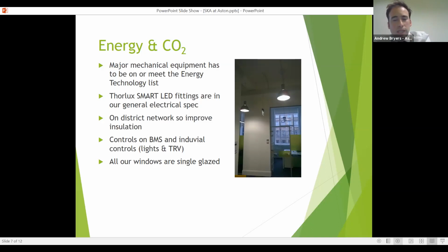We only have single glazed in our main building where we've done the main projects so far. We haven't done it for any other building, but they're all really drafty. So what we always do anyway is completely refurb the windows, make sure they're closed, make sure there's no draft, and that we repaint them, reseal them, and recork them, and so that helps meet the scopes anyway.